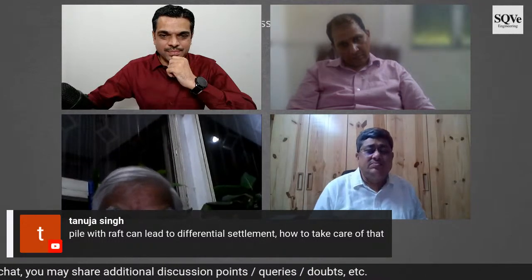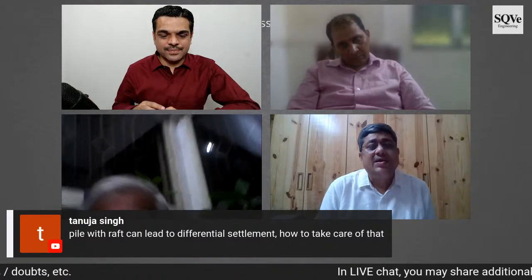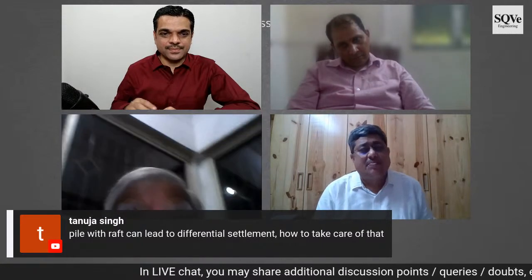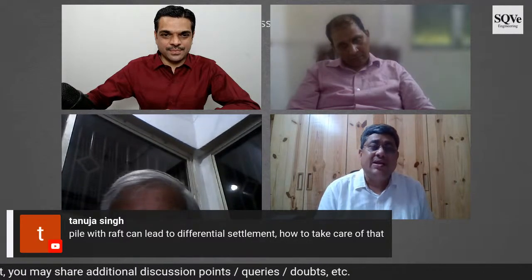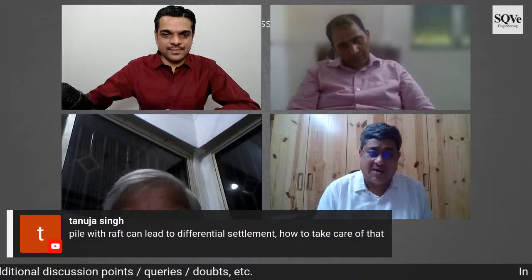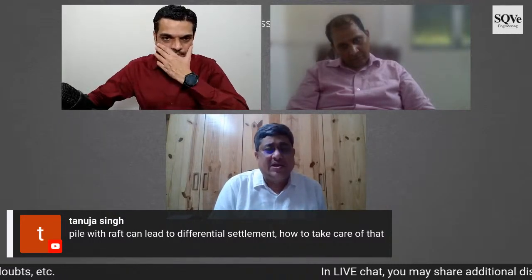Generally, what we are doing is designing the piles when we have already gone for piles. So instead of giving a pile cap, we combine this pile with the raft, and partial load is transferred through the pile, and the rest of the load is transferred to the raft. Each and every foundation should be treated individually for settlement, and the settlement value should be equally done for all the cases.